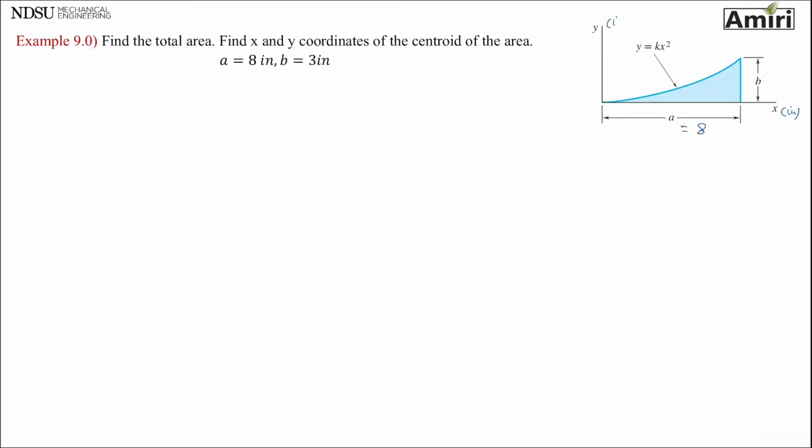and b equals 3 inches. All right, x and y coordinates of centroid. I'm going to work on that one because that also includes the total area. So while finding x bar and y bar, then I can find total area as well. So let's write our equations first. Integral of x tilde dA over integral of dA.